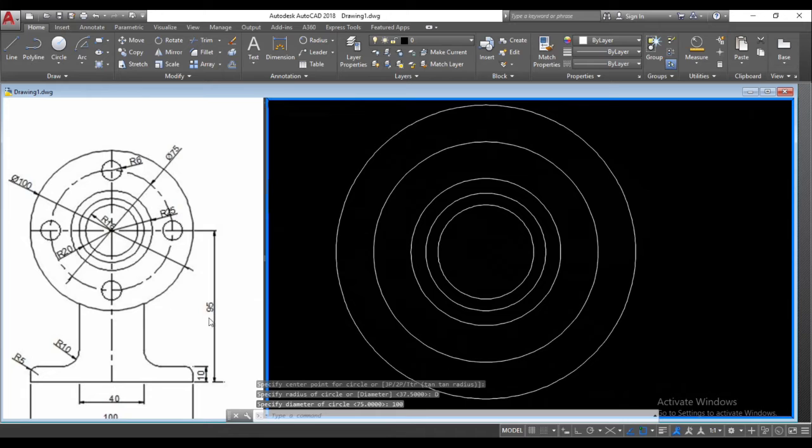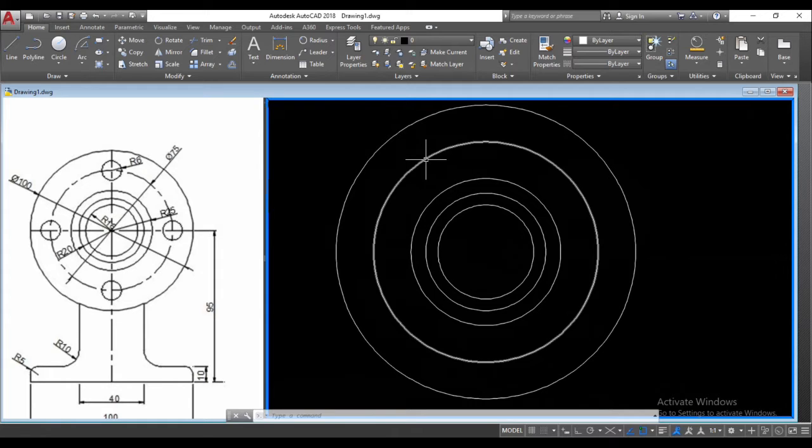So we have all 5 circles right here, and we could just go ahead real quickly. This one is indicated as a center circle between these 2 points, so I am going to change the type of line. If you notice over here, this is the indication of a center line, a long stroke with a short one with a long one. So in AutoCAD, you have the ability to change your line types. So you're being introduced to line types.